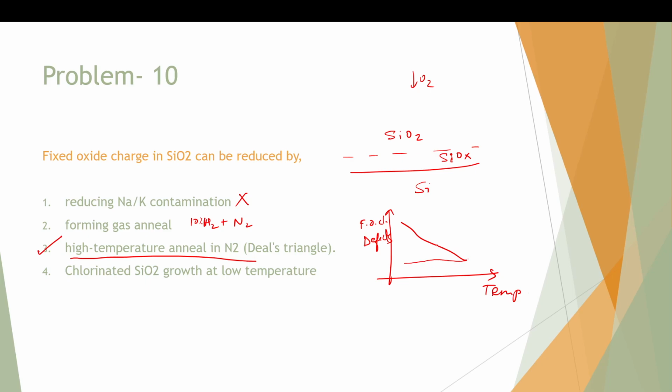So this is when there is oxygen ambient; had I done nitrogen ambient at this temperature, it would have dropped down. It just means that we can do as much oxidation as we want, and after the oxidation is done, if I just do a high temperature anneal in nitrogen ambient, then I get a perfect SiO2 layer on top of silicon, with minimum defects. So this part of SiOx will reduce and become very thin.